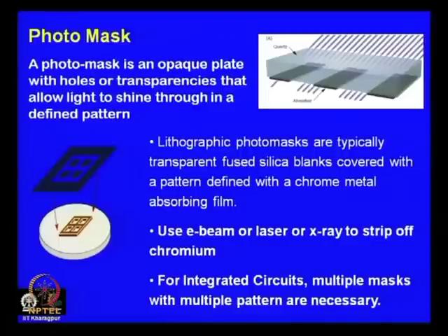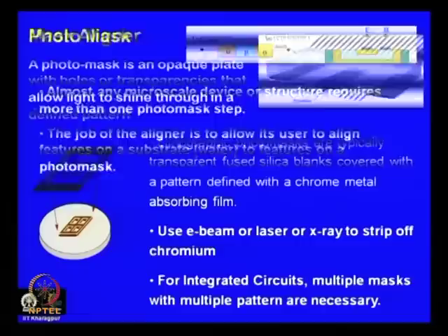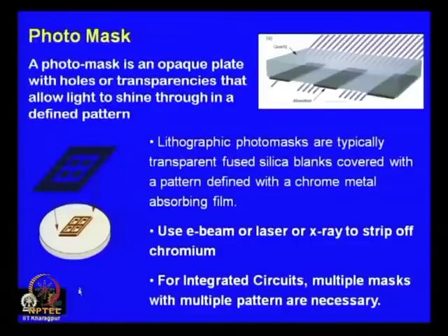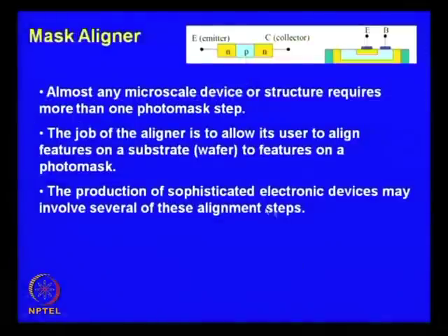One mask apparently sounds pretty simple, that if you have a piece of mask, a proper photoresist and a UV light source, you can implement your photolithography. But as we will see, it is industrially much more complicated, since you might have to use multiple masks with multiple patterns, and these are not random patterns you want to create. These patterns will be coherent to the earlier pattern you have created. So, something like this.